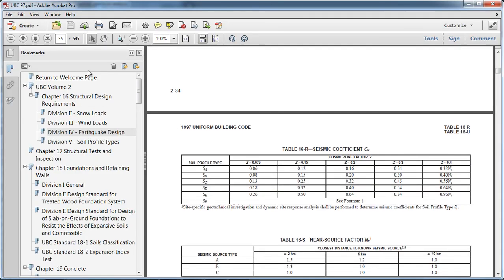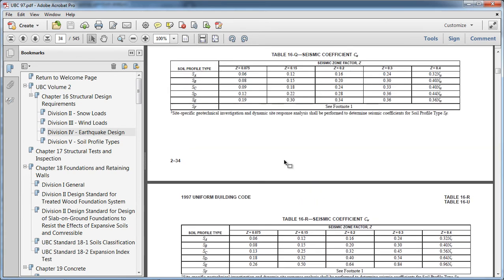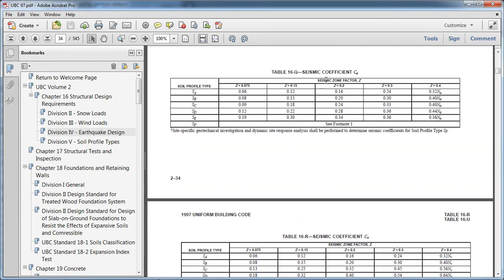At pages 34 and 35 you can pick the seismic coefficients, acceleration base and velocity base. You pick your soil profile type, either SC, SD, SE, and then in which zone your building is going to lay, for example zone 1, 2A, 2B, zone 3, zone 4. For example I am selecting zone 3, and soil profile SD.